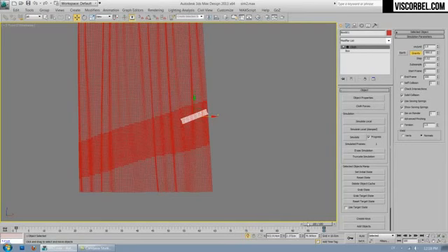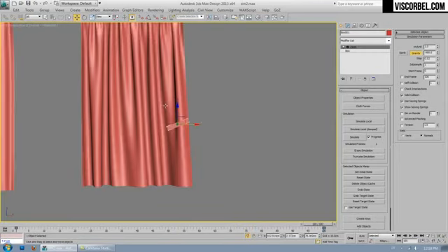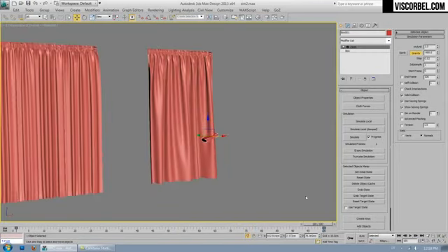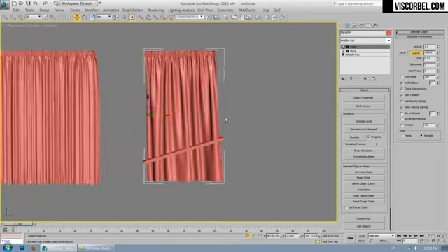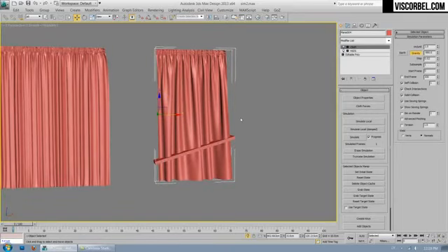Right. So now that we have changed our animation, I think it's gonna be fine. And I can run the final simulation by going to my cloth object, enabling self collisions, check intersections. And now I can just press the simulate button and wait for it to finish. Go make some coffee or something like that.